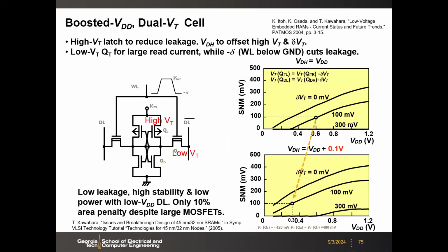Okay. So then also you can do something differently if you have different transistor VTH, right? So what you can do is, let's say for the latch in the middle, because you know the leakage current goes through here, VDD to ground. You have two transistors suffer from that, from each branch. So you can use some higher threshold voltage, which means lower leakage current for those transistors in the middle.